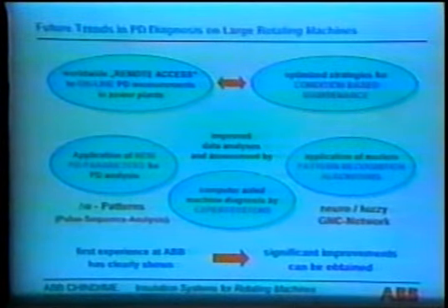Finally, I will show you some future trends in PD diagnosis on large rotating machines and a concept for stator winding insulation diagnosis. One point is the worldwide remote access to online PD measurements in power plants to optimize the strategies for condition-based maintenance of the machines.